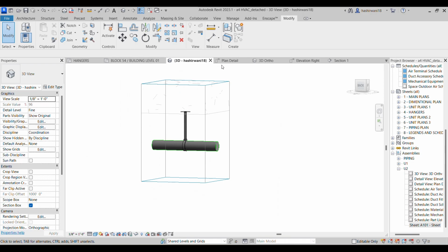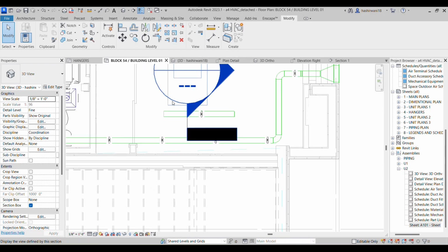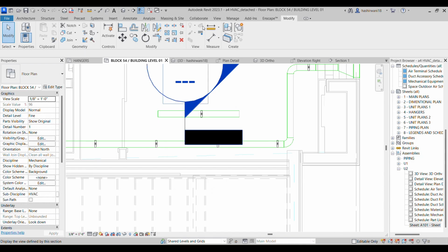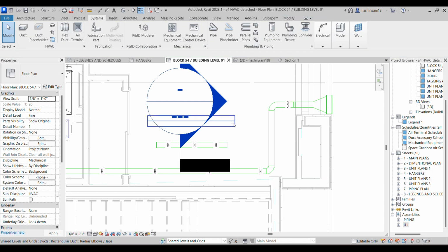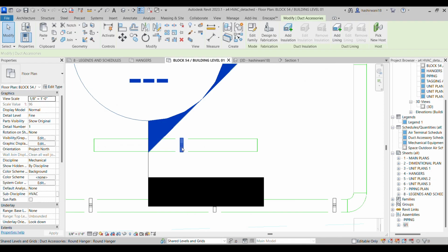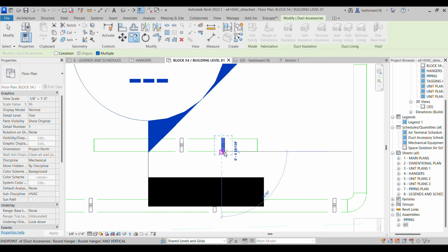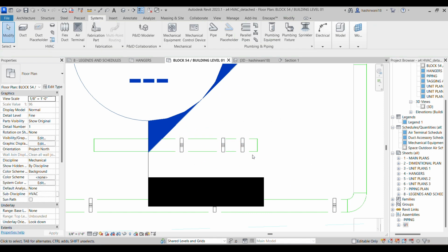So this hanger has now been placed correctly. So what I can do is I can go to the view, I can simply select it. So guys, what I am going to do here, I'm going to be deleting these particular things because I'm going to show you how we copy these hangers. So I'll simply copy it and use this command here, copy from this base point, and if I want many particular handles according to the standard, I can place.